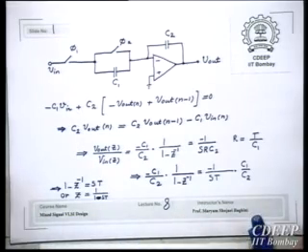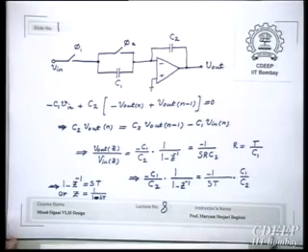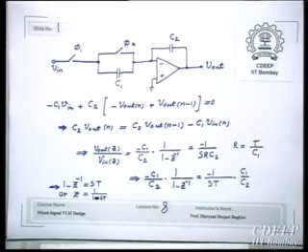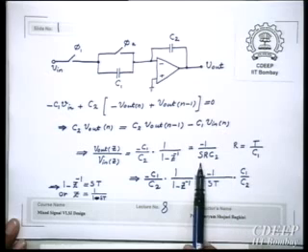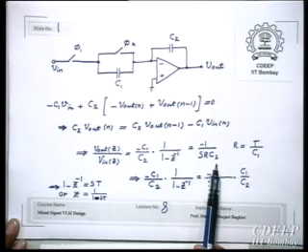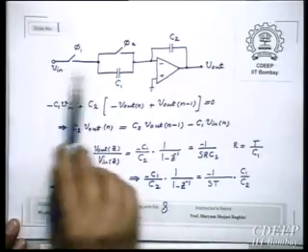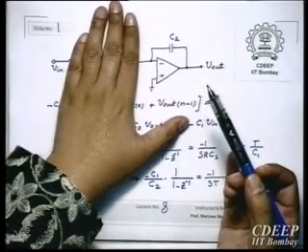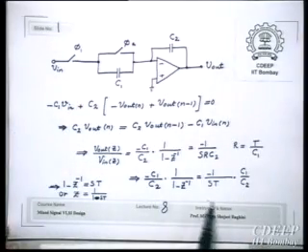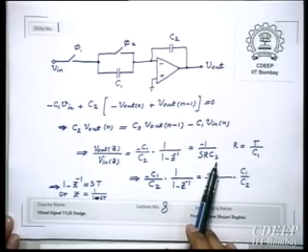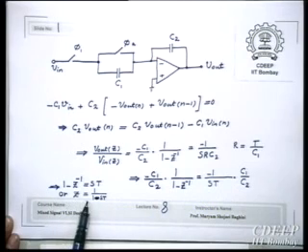Do you remember I told you, you check it for integrator? This is like one way of checking. How can we get that integrator approximation using this interesting switch cap circuit? So, just I equal it with -1 upon SRC2. R is emulated by C1, right? And 2 phases phi 1 and phi 2. This part is as before, right? Therefore, I have RC. So, just I make it equal to -1 upon SRC2. Therefore, I will get relation between S and Z. And this tells that Z is equal to 1 upon 1 minus ST. So, this is backward Euler.